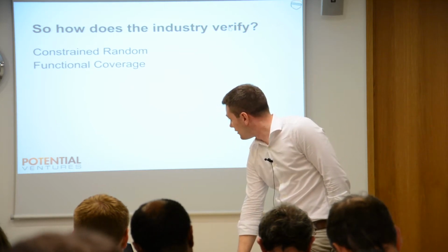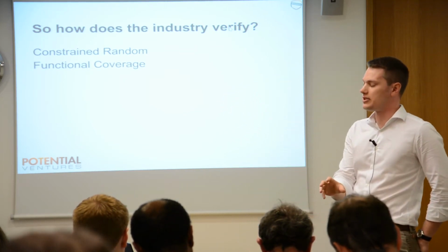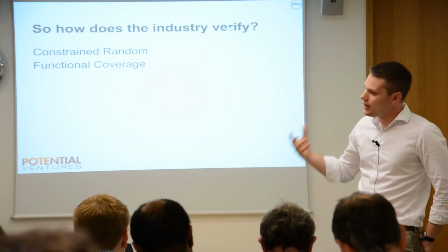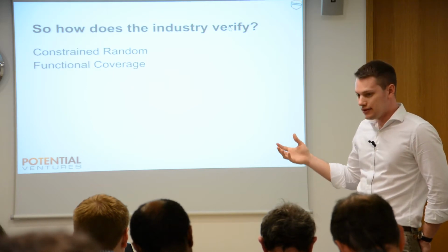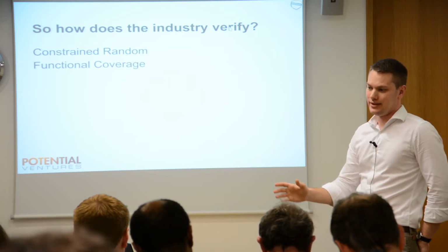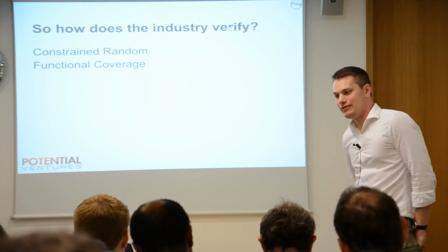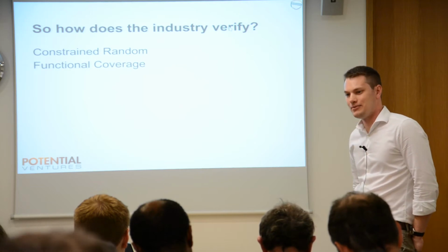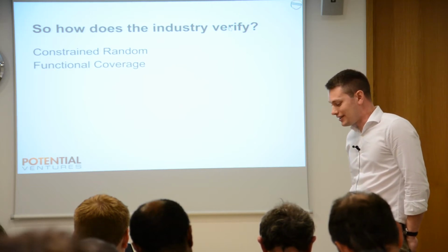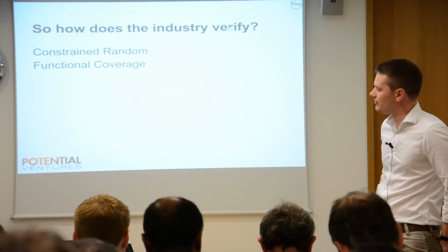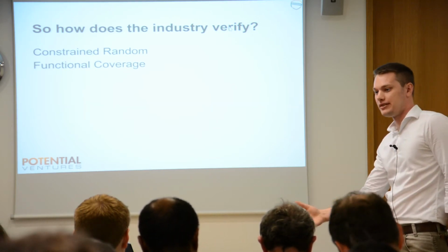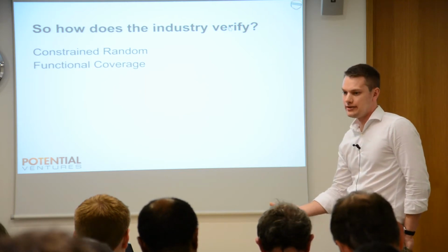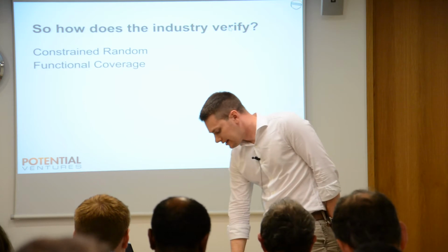In theory, if you've got a model of how the system should behave, and you've got cover points tracking how well you're doing in verification, then you can just throw CPU power at the problem, and you know when you're done. You just wait until you've generated every possible scenario that is interesting to you, and you've got a working chip, in theory. In practice, that's often not the most efficient way, so you combine some random stimulus with some directed tests. You want fast running regressions, for example, continuous integration, things like that.